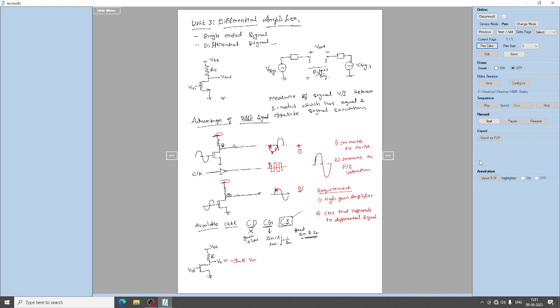So this can be written as input V in with respect to the source terminal 0, right? So we can write the output expression as minus gm into r times V in minus 0, considering the two terminals of the circuit, so that we can modify this circuit to give the differential input now. Okay, to give the differential input.